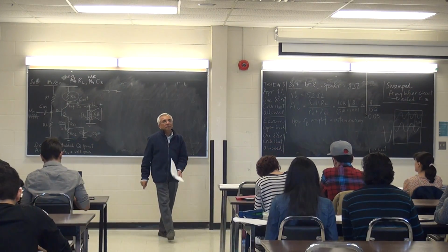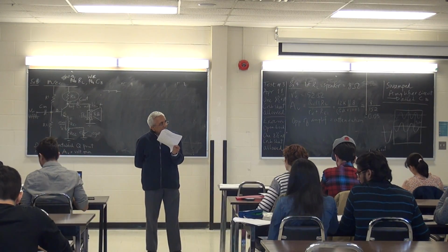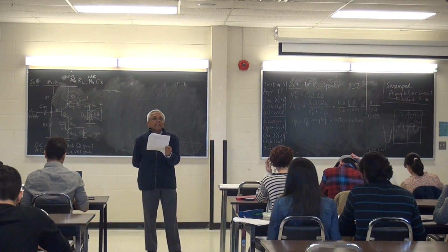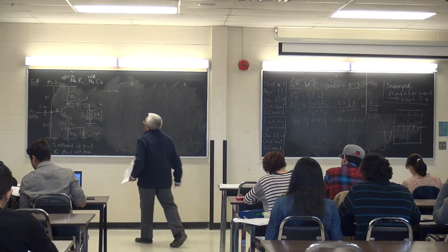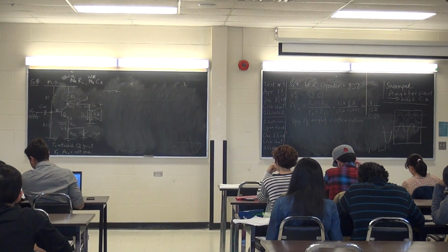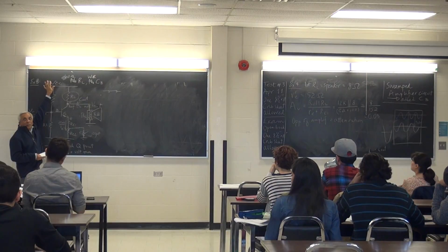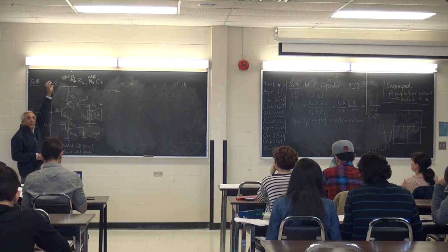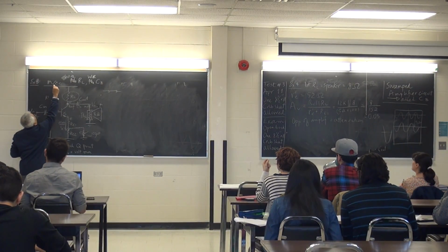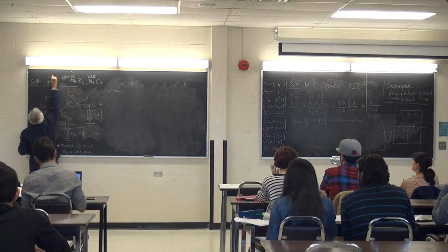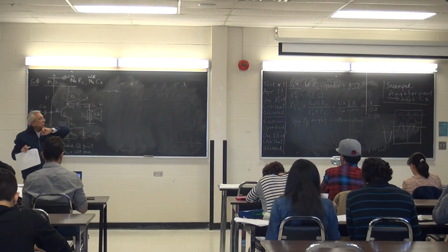Okay, closed switch. The second behavior of an amplifier circuit is that the DC source is replaced by a ground. What does that mean? What it means is this. This is my DC source. Does everybody see that my DC supply is here? This is replaced with a ground. This AC signal here feels that this guy here is like this. It feels that the DC supply is at ground potential.